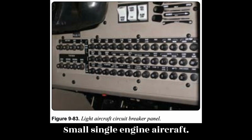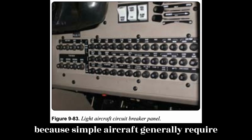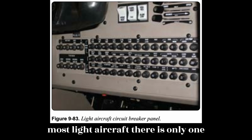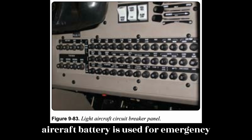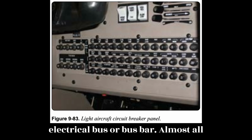Small single-engine aircraft. Light aircraft typically have a relatively simple electrical system because simple aircraft generally require less redundancy and less complexity than larger transport category aircraft. On most light aircraft, there is only one electrical system powered by the engine-driven alternator or generator. The aircraft battery is used for emergency power and engine starting. Electrical power is typically distributed through one or more common points known as an electrical bus or bus bar.